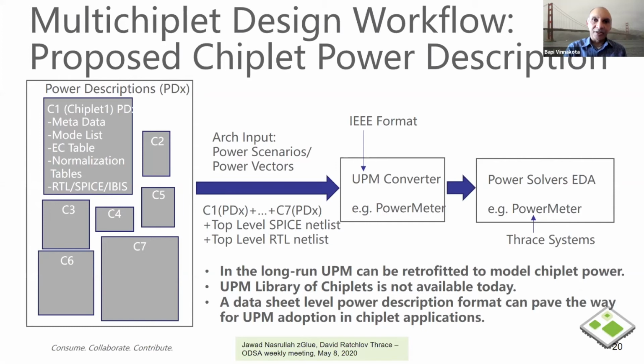The main thing here for us is this comes back to the idea that when you are developing a die, normally if you're selling the die for use in a package part, you'll have to also ship some metadata about the die. You'll have to ship information about its power profile. You'll have to ship information about the interfaces and the pin order, etc. And we're really trying to figure out, what is the best way to share that information while still preserving IP rights and while still preserving the information that you want to keep secure? Because this is typically not stuff that an ASIC vendor releases into the market.